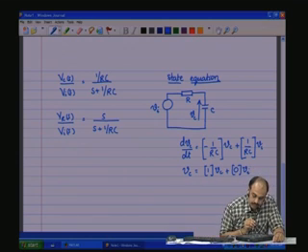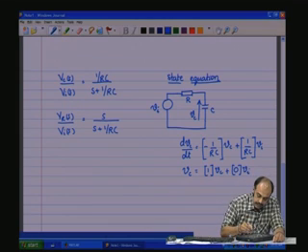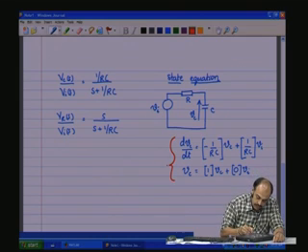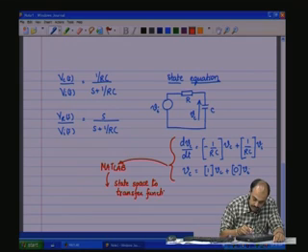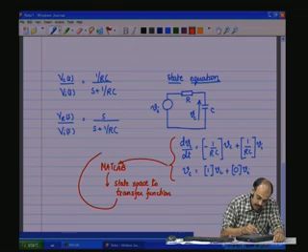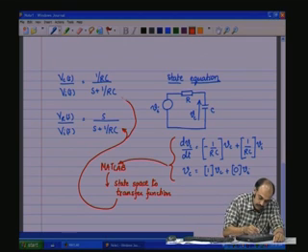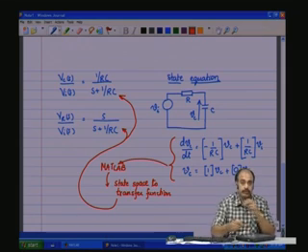Now, we shall do a small process, that is, we take this state equation model, input it to MATLAB, so in MATLAB let us make a conversion from state space to transfer function model and obtain these models depending upon what we want to give as the output variable that we want to see.